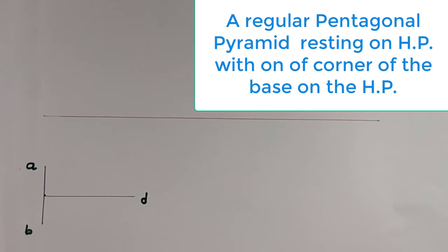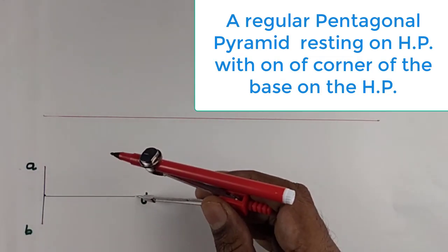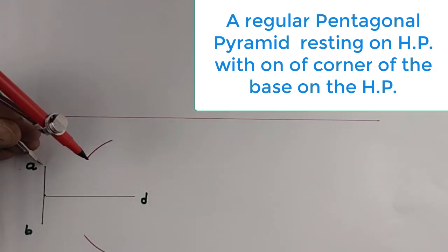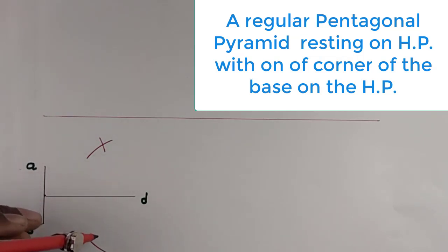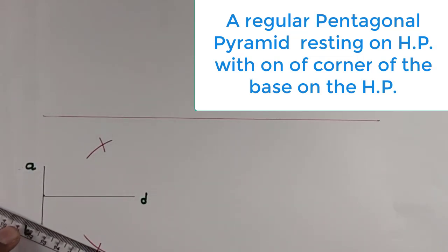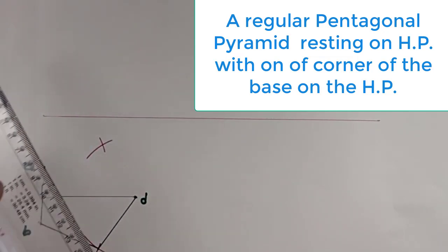Now we create our pentagon by using the radius, the side of the base AB. Keeping D as a center, draw the arc on both sides. Similarly, with corner A as a center, draw the arc on top, and choosing the corner B as a center, you can draw the arc on bottom. Now you can join your points with a straight line. This is my corner C point. This is our side CD.